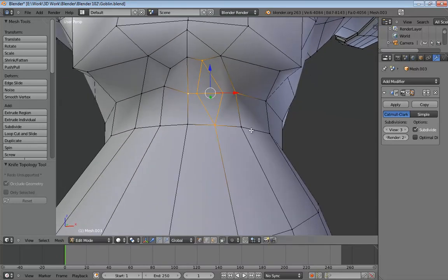Now notice, I'm finished now, and I'm not saying you ever want to do this, okay? This is just an academic case in point. Notice that I'm now finished, and I have everything back to quads and triangles. But in the process, during the construction period, I was able to just wipe out everything that was in my way and create brand new geometry, something that was impossible before, because now I'm able to produce these n-gons.